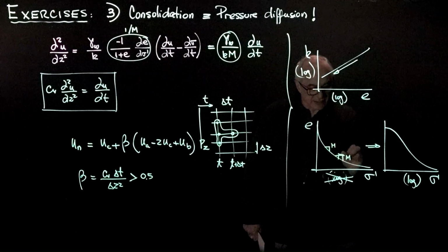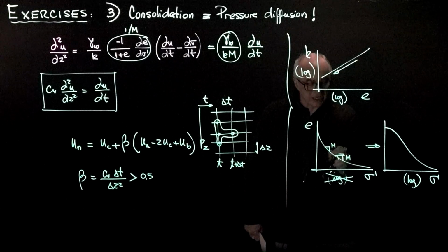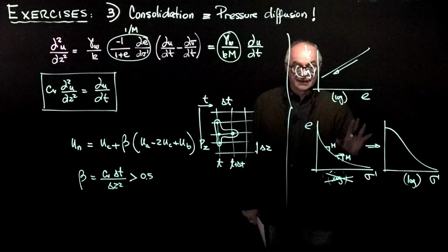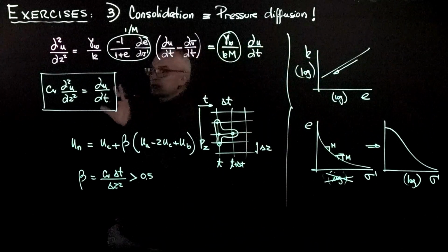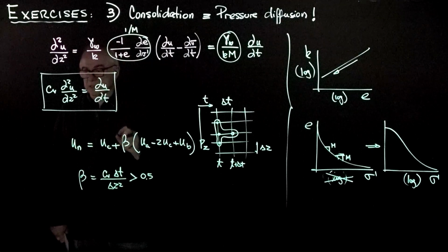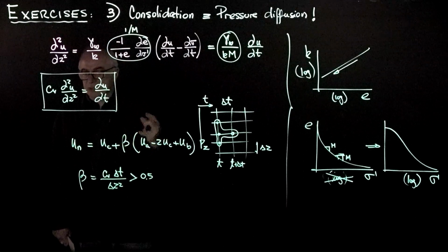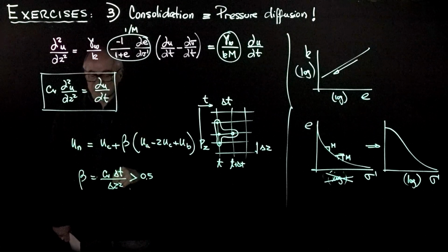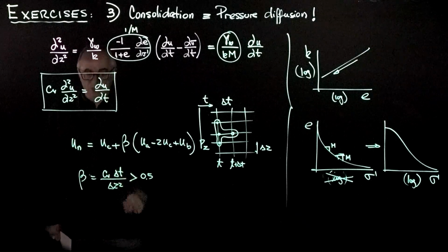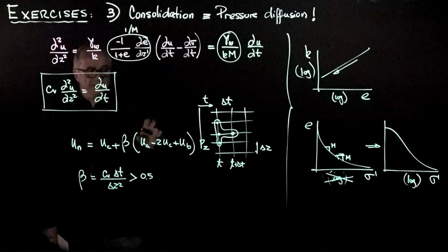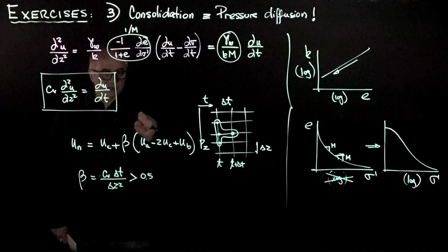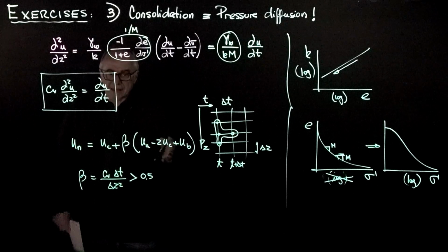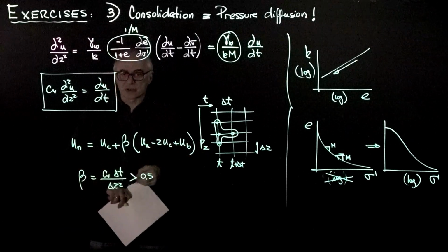And as you can see, the constraint modulus is indeed changing as the void ratio decreases or the effective stress increases. Now, in order to get to this equation, we assumed that these values were constant. But if this is a bad approximation for your problem, please go higher up in the stack of the derivations and use the right form of the equation. With this in mind, let's come back and solve a problem which is quite relevant for all laboratory testing and is the basis for the interpretation of field data as well.